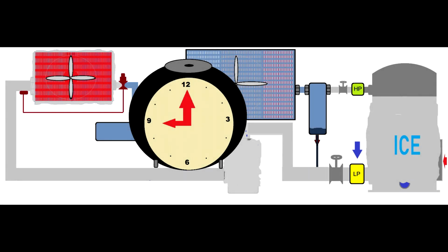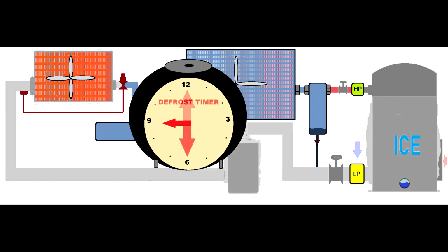To avoid this phenomenon, we apply defrost, but many systems use defrost based on time. It will be a timed defrost which will enable a heater element or invert the refrigerant cycle, so we push hot gas into the evaporator to melt the ice. This is a choice, but not the best choice, because the timer disregards the environment.